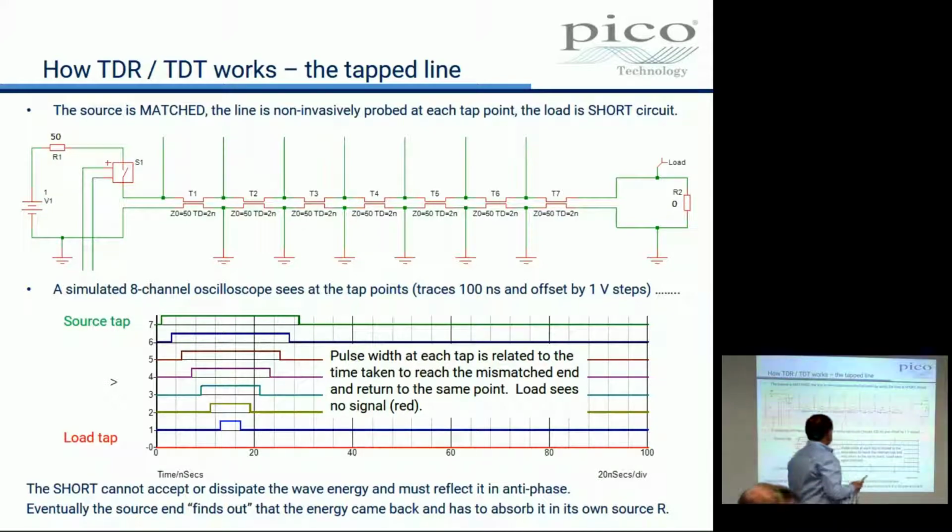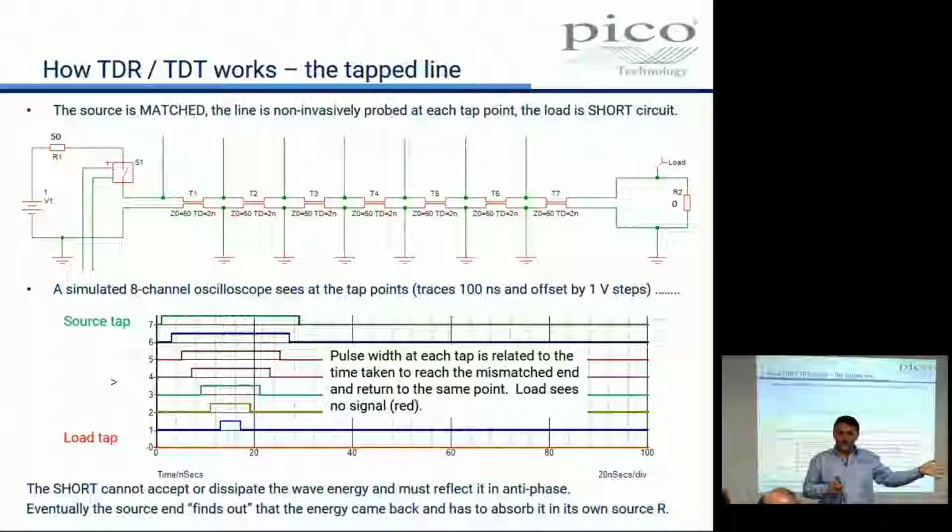Okay, so strange things happen in cables that have a length that is relevant to our measurement. I say this because we're going to be thinking with a VNA of relatively high frequencies traveling in cables and in PCB lines, but even on the national grid, 50 hertz is a problem, as we'll see later. 50 hertz traveling along 100 kilometers of cable and coming to a short circuit does some really nasty things.